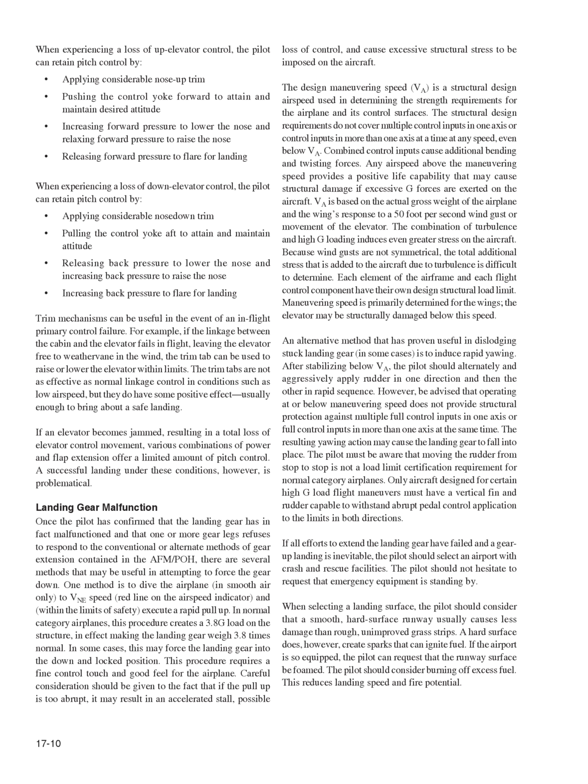Landing gear malfunction. Once the pilot has confirmed that the landing gear has in fact malfunctioned, and that one or more gear legs refuses to respond to the conventional or alternate methods of gear extension contained in the AFM/POH, there are several methods that may be useful in attempting to force the gear down.